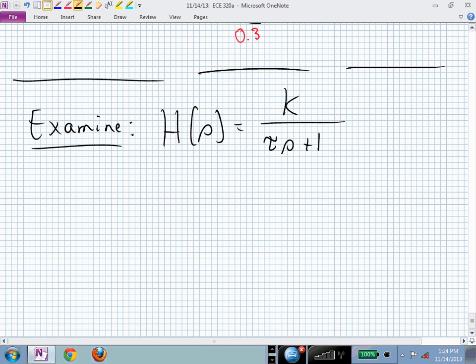And we know what the Bode plot should look like in terms of the magnitude response of that. It should be flat in our straight line approximation and then go down at what frequency? 1 over tau. And we know that at that frequency, in fact, we'll be down 3 dB, or this absolute value of 1 over the square root of 2. But let's now see if we can understand where some of these terms come from.